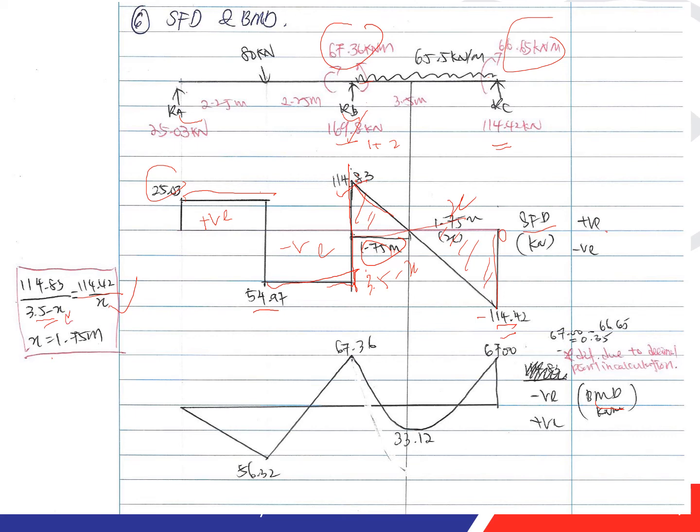So this is from the mechanics of materials, so I won't repeat much here. You already calculated this, already completed this. Now you need to draw the bending moment diagram. Don't forget you have a bending moment here. The shear force diagram does not consider the bending moment, because this is the force diagram, not the bending diagram.